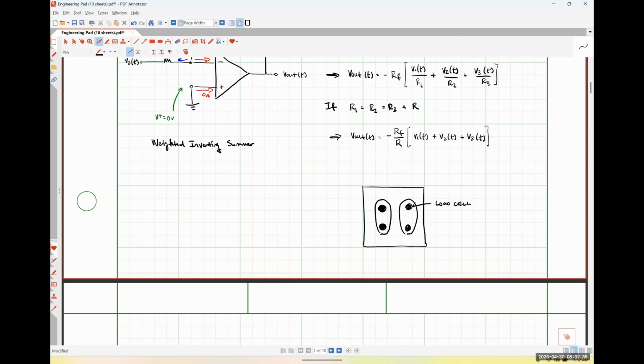Well, that computation is performed by an inverting summing amplifier, because all of the signals are going to be scaled by the exact same amount. And the ratio of those resistances is just whatever I need it to be to convert whatever the output signal of this guy is.